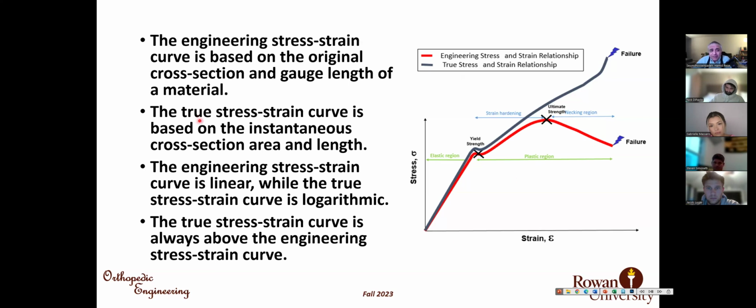But if we use instantaneous L, for example, we apply a stress here, we have a strain, so L was without a stress, and we have a delta L divided by L become the strain here. When we apply another stress, we have another delta L2. We divide this delta L by the L2 here, not the original L. So if we have any change, we divide it by the L in the previous step of the test. That is why the result will be almost a linear curve.